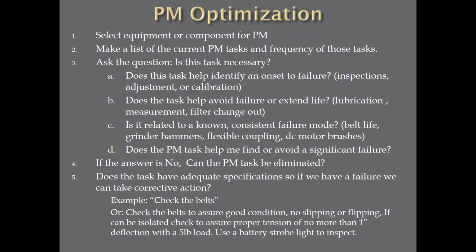The last question, does the PM task help me find or avoid a significant failure? You know, if you answer no to those questions, it says here, can the PM task be eliminated? Number 5, does the task have adequate specifications? So if we have a failure, we can take corrective action.